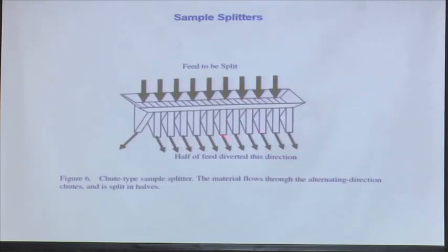And a sample splitter that is called a Riffle sampler. You have got riffles, and oppositely they are basically oriented 50% to this side, 50% to that side. You take your material in a container like this, bring the material like this, and then pour it so that it is getting distributed 50-50. Then 50% you discard, and the remaining 50% again, you repeat that until you get your desired quantity.